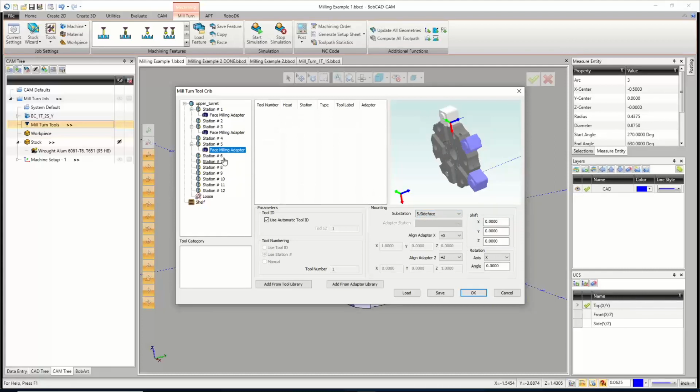And then for the final tool, so this is going to be the center drill, the 3/16 drill, 3/4 inch drill, and then finally we'll do our 1/4 inch flat end mill, which is really doing all the rest of the work. I'm going to use it for roughing and finishing. If you don't want to use it for both, maybe you have a roughing version of your 1/4 inch end mill and a finishing version, then you're going to end up having to put 2 of them in here. And it'll help if you pull one from the rough category and one from the finish category.